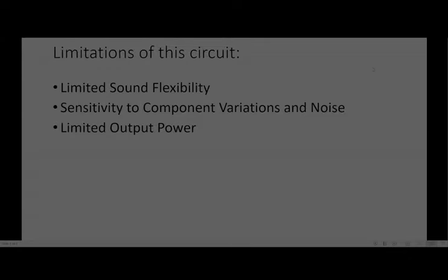But the range of sounds it can generate is limited. And since the project uses analog oscillators and op-amp feedback networks, the output is sensitive to resistor tolerances and capacitor tolerances. There's limited sound flexibility. It is sensitive to noise. And since we have implemented the circuit on a breadboard only, the quality of sound might get down a bit.